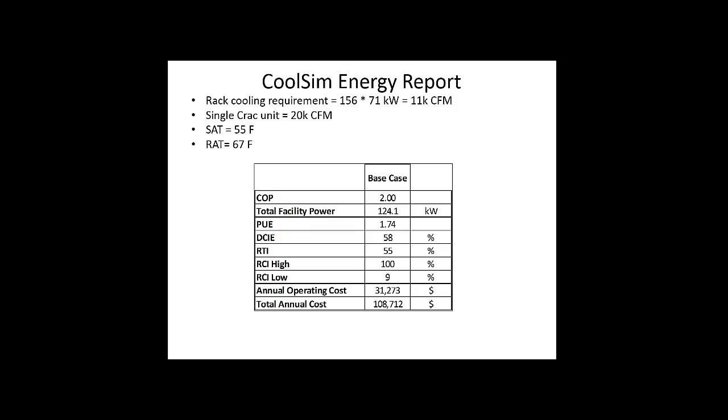Yes. I'd like to also point out that if you're running very cold and you have cold return temperatures, one of the things you run into right away is that the capacity of your cooling system degrades. Oftentimes you buy these cooling systems based on a tonnage, that's the old English system. So if it's a nominal 4-ton cooling capacity unit, that assumes that the return air temperature is in the 80s. If it's not, then it's not a 4-ton unit. It's much less than that, and it declines pretty quickly. Furthermore, it has to run a lot harder, and that means energy, and of course, it reduces its life.